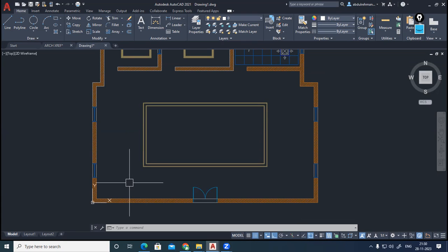Your structural layout for the same layout. And also, suppose if you are working everything in a local server system, it is easy. But even so, if you are working in different systems, HVAC might be done by a separate system. Plumbing will be done by another person in another system. When you are combining everything in a single drawing at final coordination time, your base point should be proper. Then only, one above one, can we place the services perfectly and do the coordination.